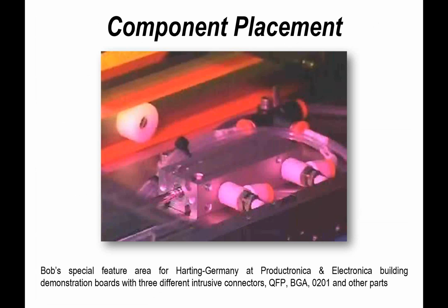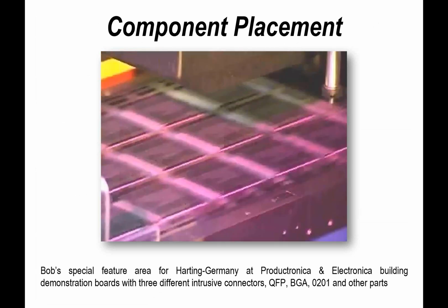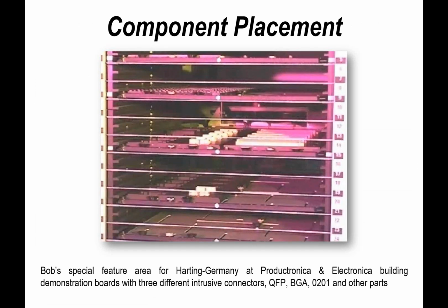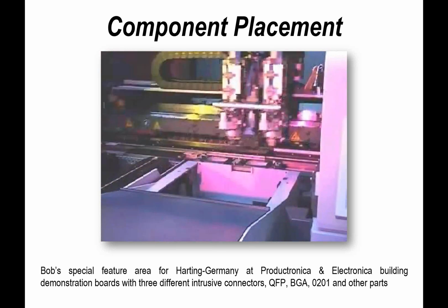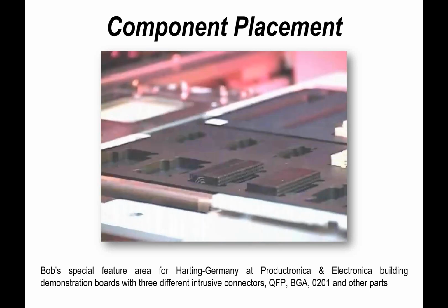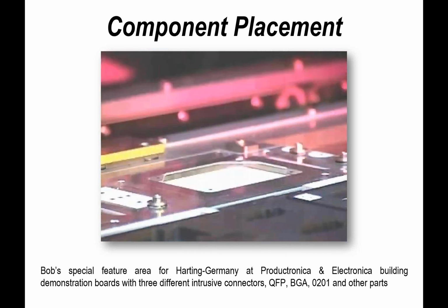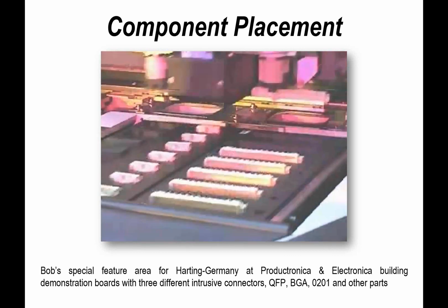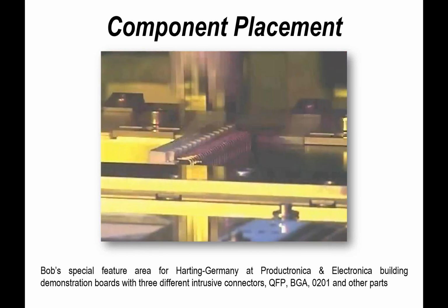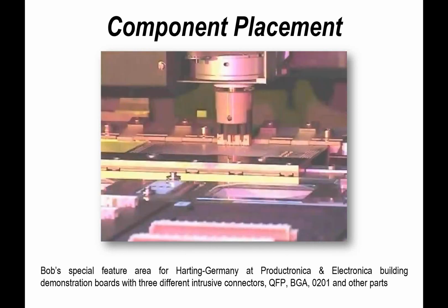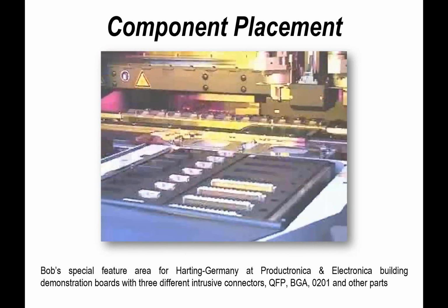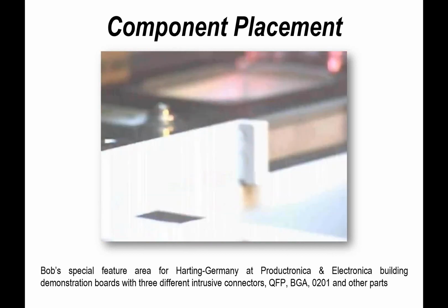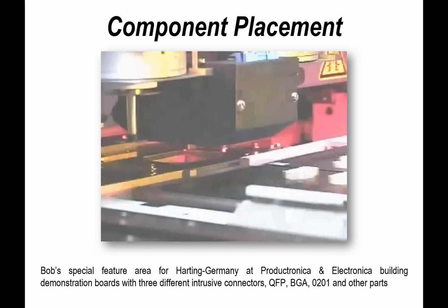This is just an example of a production line where I was running 4 different types of connectors on boards. So we were stencil printing, we were assembling these particular connectors to the board, along with BGA and all the other sexy components as well, at a live demonstration. And on some of these parts, I was using preforms to increase the volume of solder to specific joints. So I could actually demonstrate the difference between using it just with screen printed paste and non-screen printed paste.